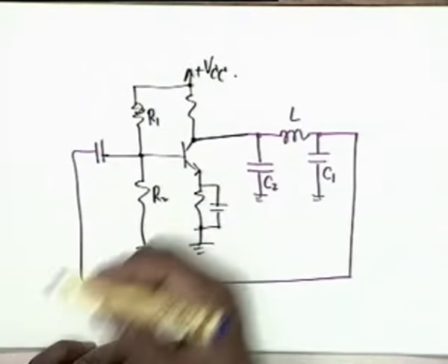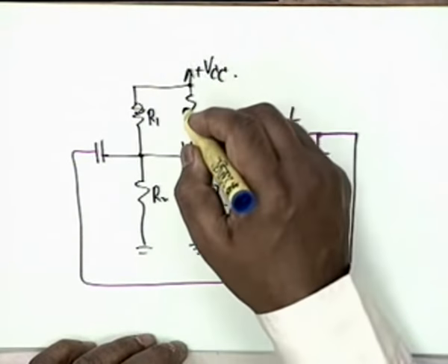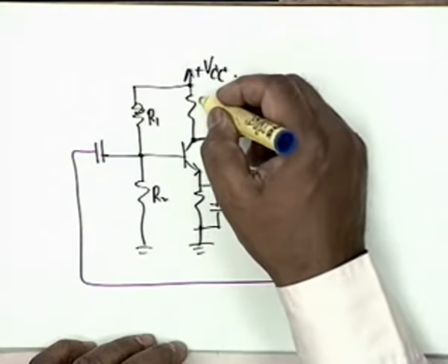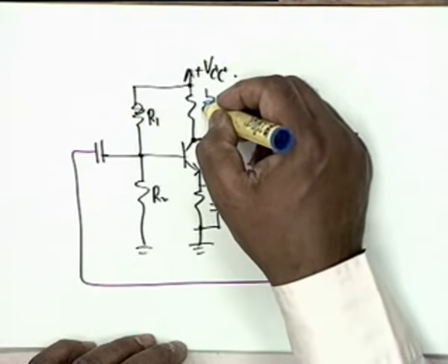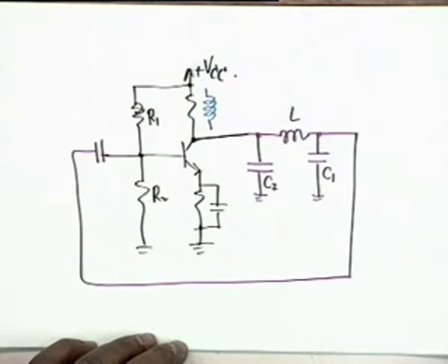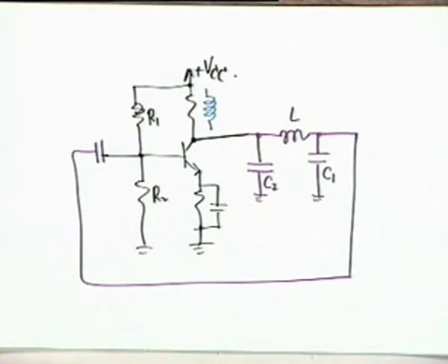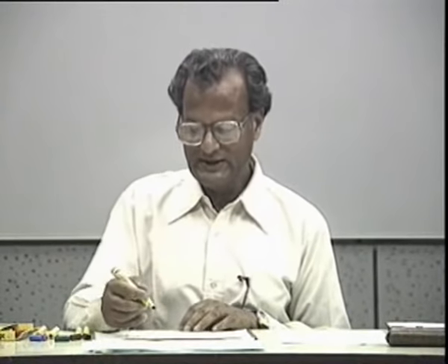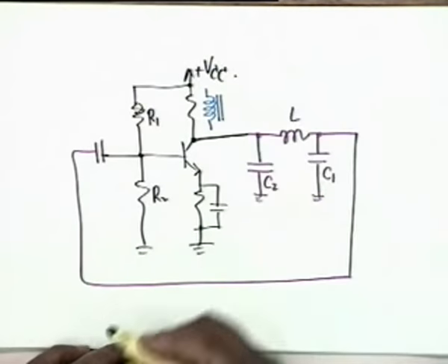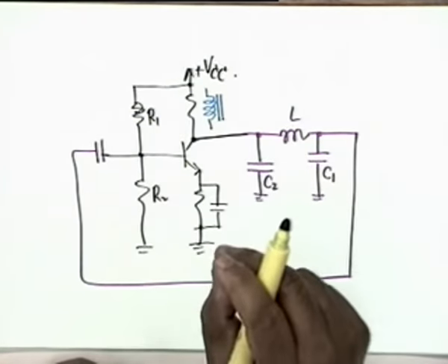So what one does is, instead of using a resistance, one uses an AC load, which means you replace this by means of a high valued inductance, because you require a gain of, ideally, 3, but one uses a high valued inductance so that there is no DC dissipation in this, and high value can be obtained only by putting a core.